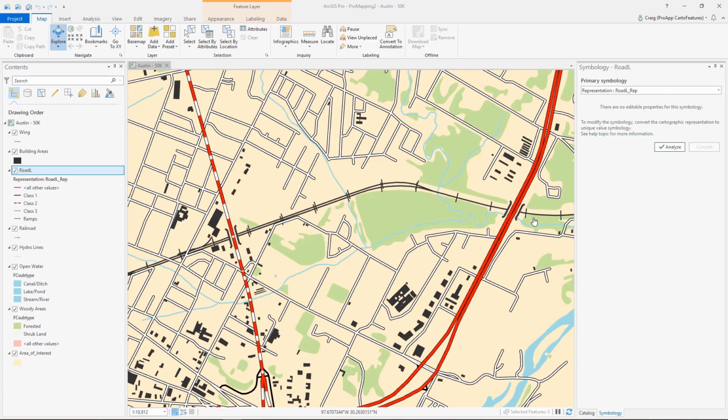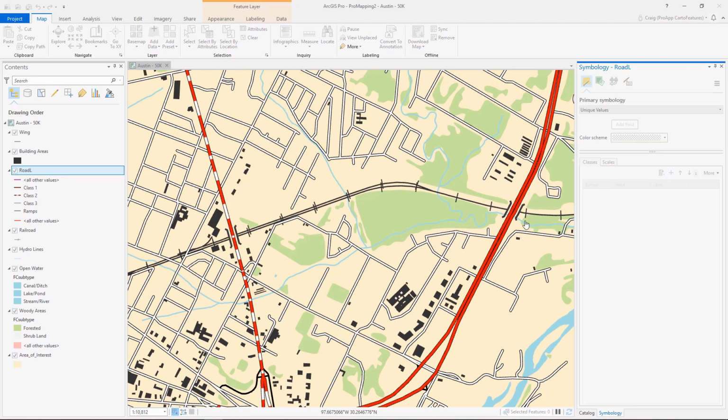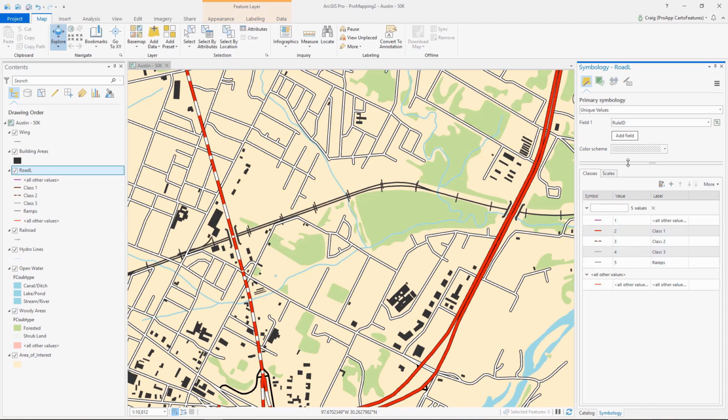The ArcGIS Pro Symbology model supports the symbol capabilities and attribute override capabilities of representations. To migrate representation data, you can now analyze and convert representations to this new model that will then convert it to a unique value renderer, where you can further take advantage of symbol capabilities in ArcGIS Pro. This also includes things like feature masking.